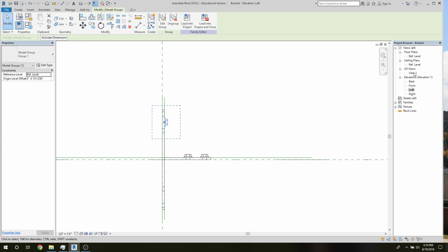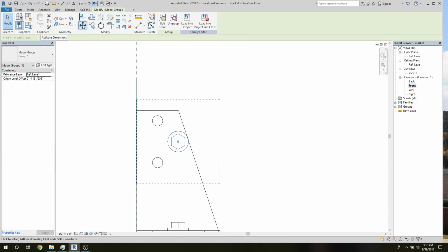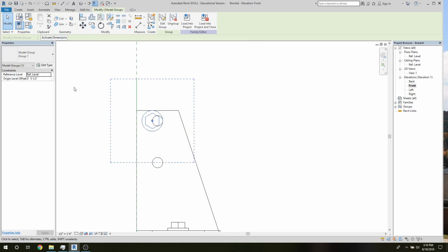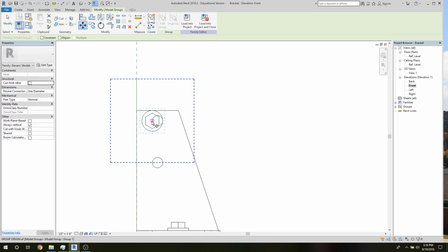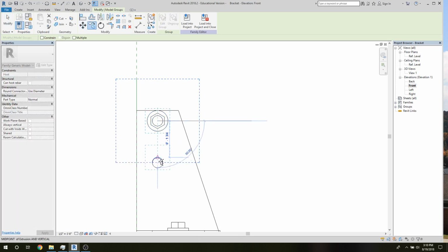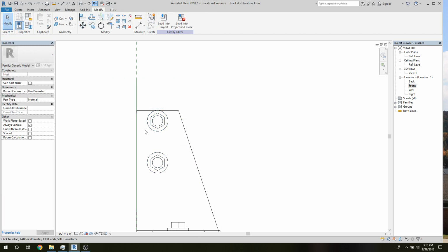And now we have to worry about aligning it. So we'll go to the front elevation. And we'll see what we can get as far as an indicator for alignment. Once again, we don't get that front view, but we do get a point that we can touch over there, and then we can move it over. And that would be a 1/4 inch to the center, and then we'll just make a copy. We've made those 2 inches apart.